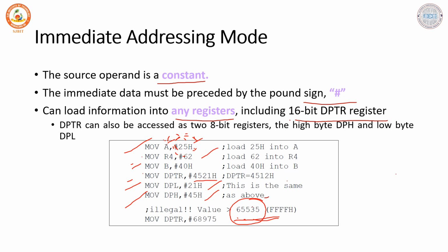The instructions here, what we have seen for the immediate addressing mode. Here it directly takes up the value and loads it to a specific location. Now there are some features included with immediate addressing. In case of immediate addressing mode, they are quite fast, because you are directly loading the value to a particular register.